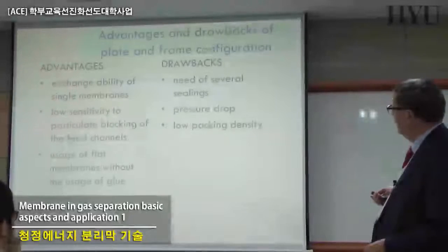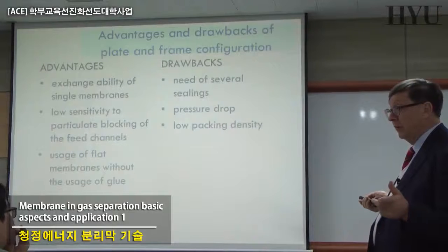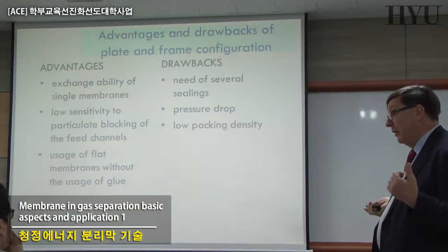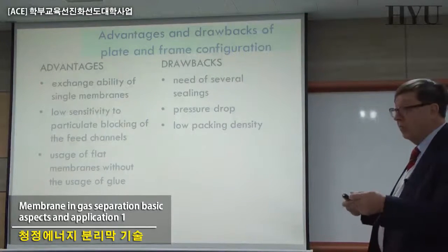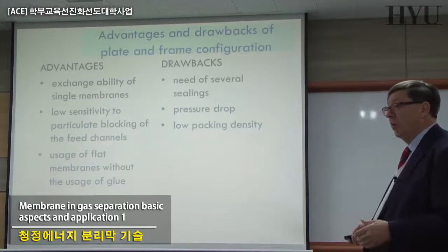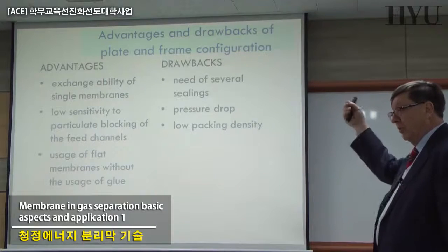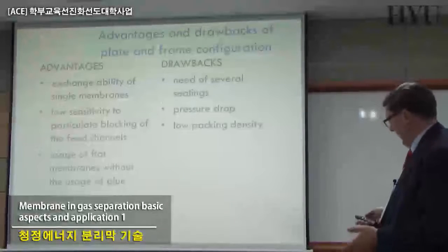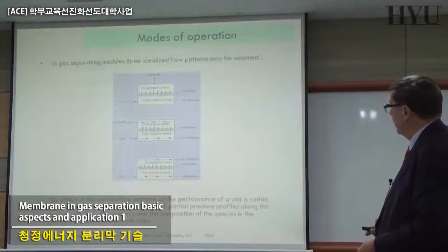In this plate and frame, there is sometimes a lot of sealing, and the pressure drop can be significant, and it has relatively the lowest packing density compared to the other configurations. On the other side, it's very easy to change membranes. You open it, put in new membranes. You don't have to put the old module in the garbage. You can easily change the single membranes. You open the module, extract the membranes, and put a new one inside if necessary, etc. And with fouling, blocking the channels is not very easy.